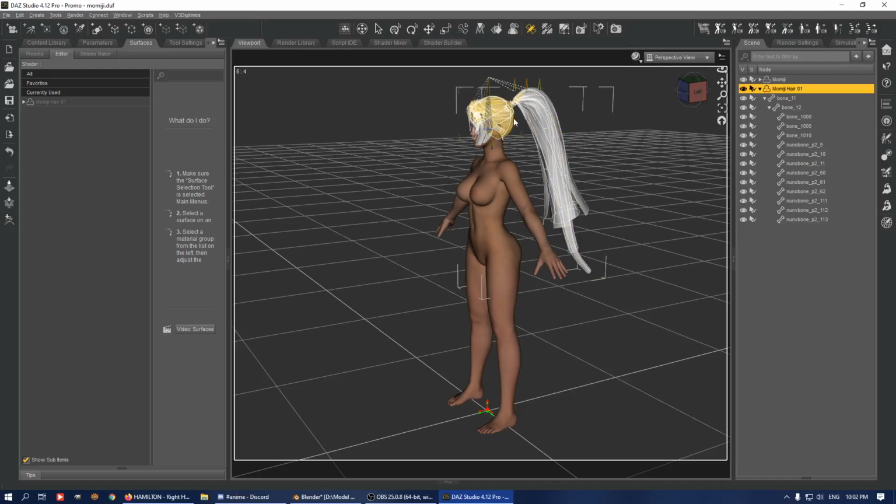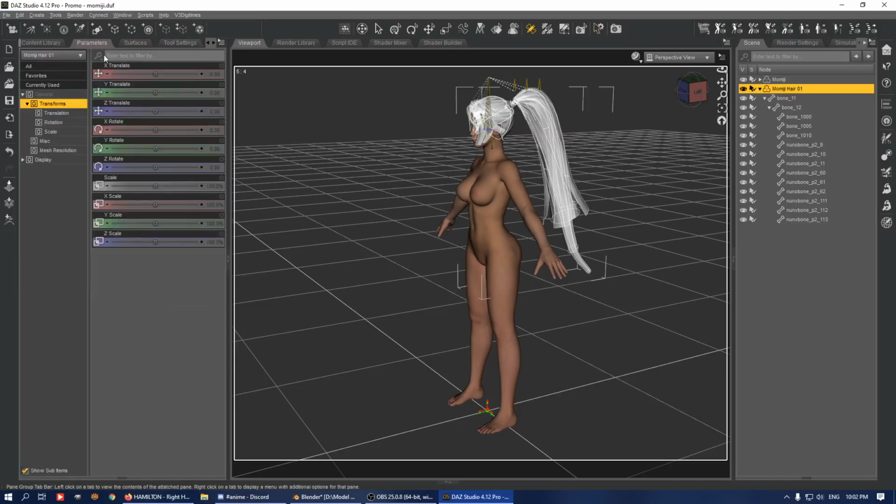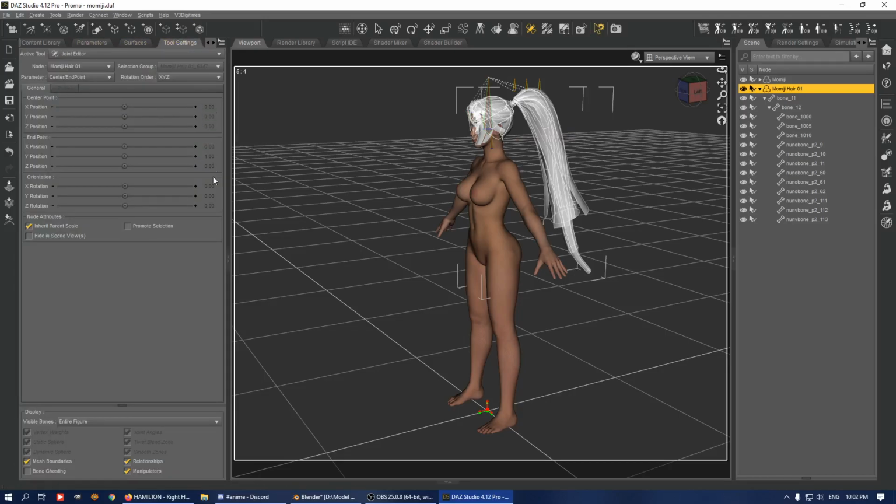For example, you save this model and then when you reopen it, the alignment will sometimes go haywire. So memorize rigging locks all the values. For example, in this particular bone, the values will all be grayed out. That means these are the new defaults, right? Once that happens, it is basically quite safe.